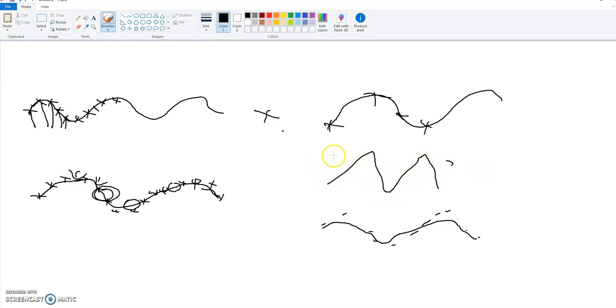So the least amount of samples, measurements, that you can take is at least double. I like 4 times. 4 times is much better, because if you have 4 values, you can see that sine wave more clearly. With 4 values you can see better, whereas with double the highest frequency, it really just looks like a triangle. So Nyquist rate: double the highest frequency.